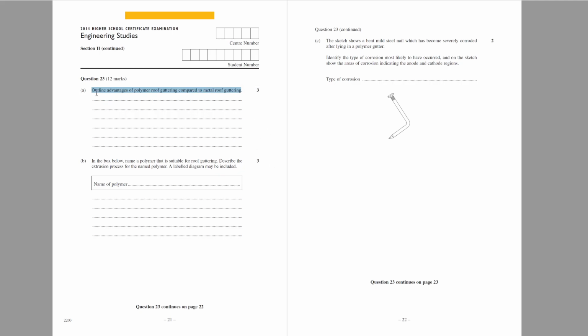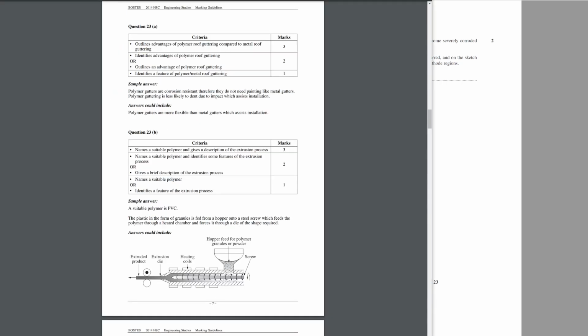So we'll expand on the corrosion, and we'll say that corrosion is an issue for gutters, especially if you have things like a screw. If you have a screw that gets left in your zinc aluminum gutter, that's going to be dissimilar metals, and that can cause problems. Flashing, you've got to be really careful when you have guttering that you don't use lead flashing with aluminium gutters.